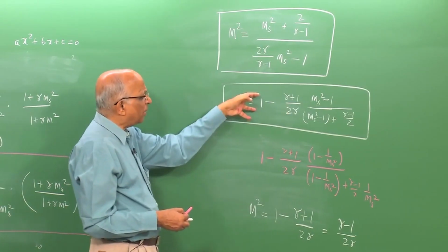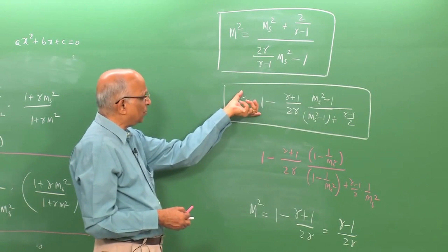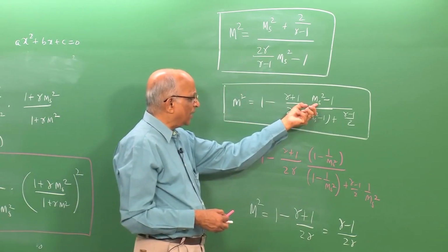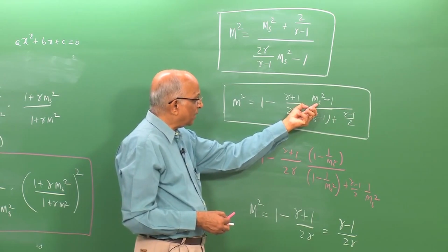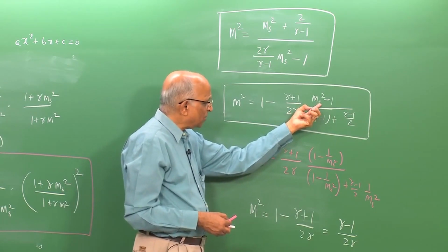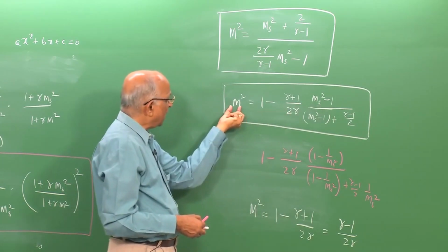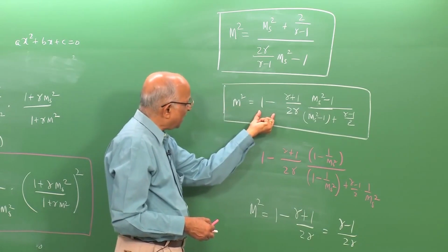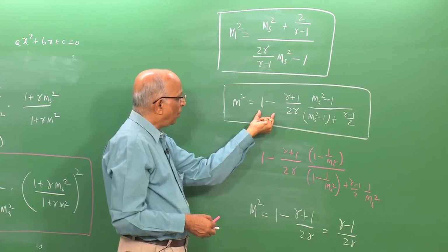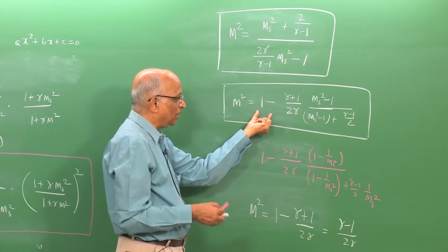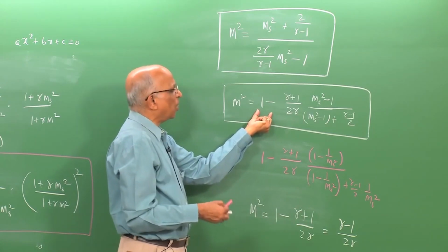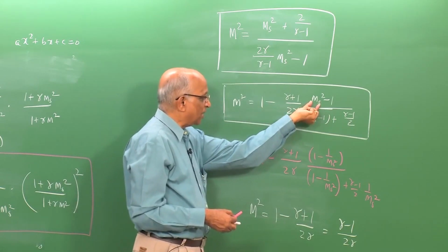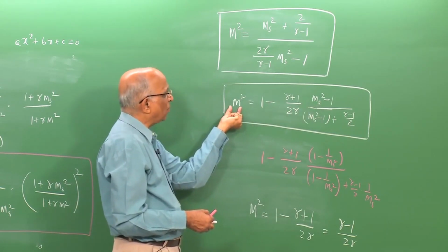But if I look at the solution of this equation, even if Ms is less than 1, in other words, if I solve for Ms being less than 1, I get M to be greater than 1. But if I look at the other parameters in this equation, the entropy decreases during this phenomenon, which is not possible, and therefore we rule out the conditions of Ms less than 1 leading to M greater than 1.